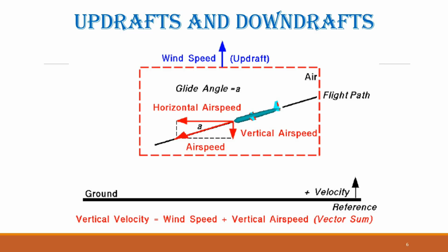All of the explanations on this slide refer to what is known as static performance. In other words, the wind is assumed to be steady, and the aircraft is assumed to be aligned with its flight path. If the wind becomes unsteady, if an updraft or downdraft changes suddenly, it can momentarily alter the aircraft's angle of attack and produce additional forces. The same is true when the pilot maneuvers the glider along its flight path by adjusting the elevator. These more complex, unsteady effects are beyond the scope of this particular explanation.